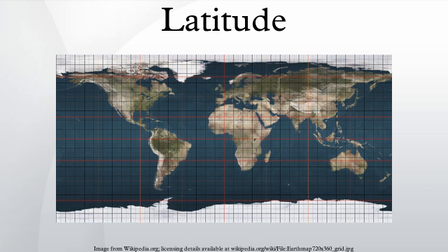The transformation between geodetic and Cartesian coordinates may be found in geodetic system. The relation of Cartesian and spherical polars is given in spherical coordinate system. The relation of Cartesian and ellipsoidal coordinates is discussed in Torge. Astronomical latitude. Astronomical latitude is the angle between the equatorial plane and the true vertical at a point on the surface. The true vertical, the direction of a plumb line, is also the direction of the gravity acceleration, the resultant of the gravitational acceleration and the centrifugal acceleration at that latitude.